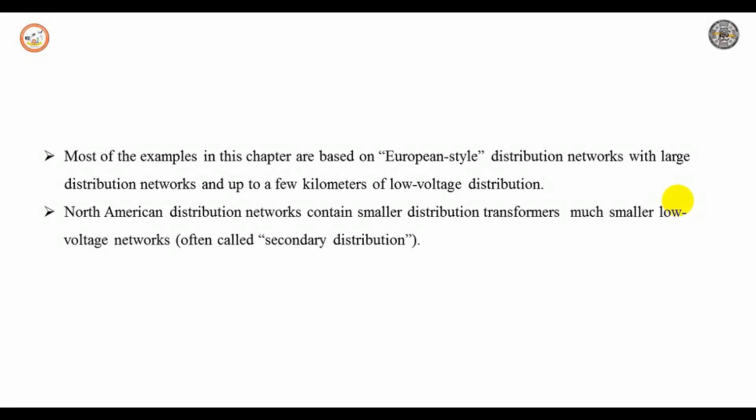Here one of the main concerns is the voltage imbalance. The voltage imbalance is also called the voltage unbalance. Sometimes it is also referred to as the maximum deviation from the average of the three-phase voltages or currents, divided by the average of the three-phase voltages or currents, which is expressed in percentage. So imbalance is more rigorous.